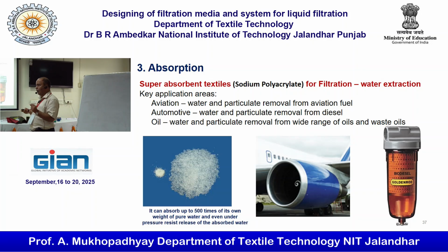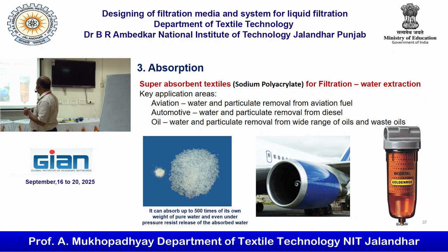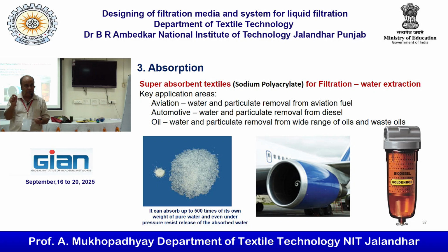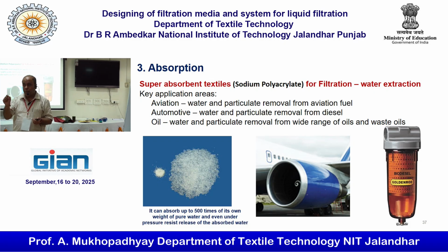That is the purpose of the super absorbent textile, which uses sodium polyacrylate for filtration by water extraction. It is used in a large number of applications where, if you have water contaminant in the fuel, the water can reduce the performance of the engine. So that water must be separated out.